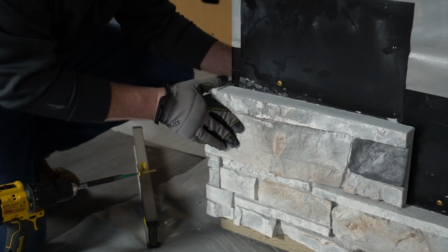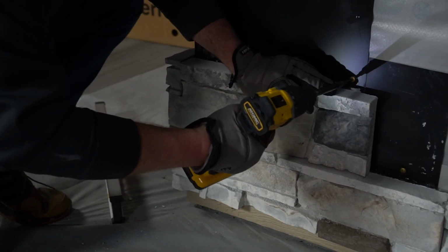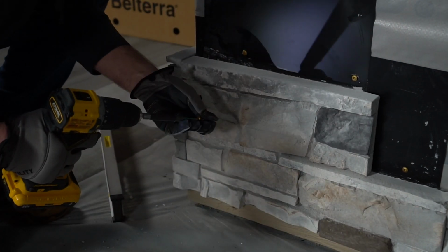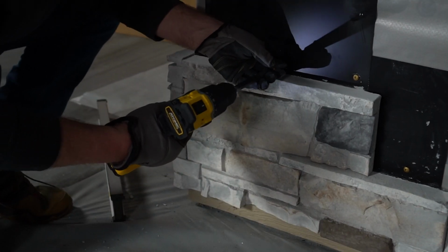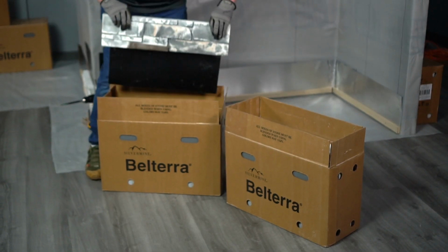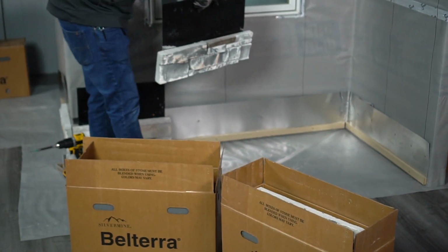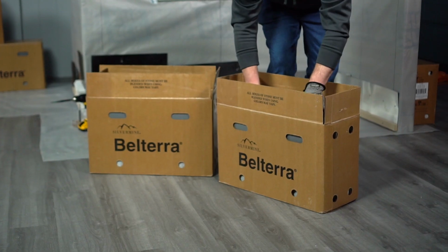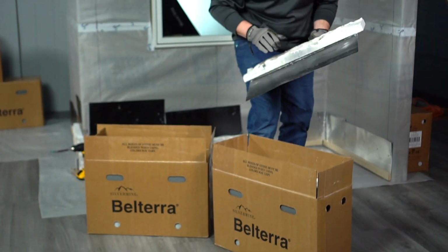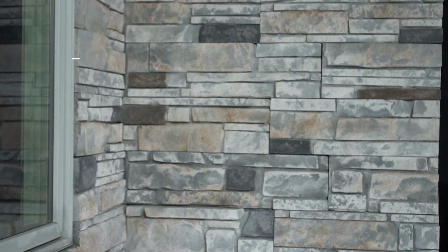When installing panels, adhere to the adage, tight is right. Panels should be installed so that they are in full contact with panels on either side. And on subsequent courses, panels need to be placed firmly on top of the panels below as well. For effective blending on the wall, it is best practice to install material from multiple boxes as you complete the installation, working your way up the wall.